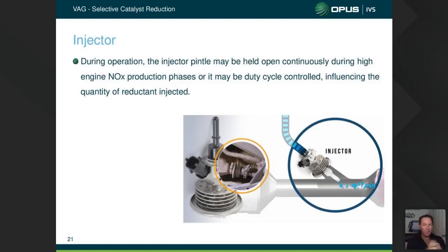The NOx reductant, or the reductant injector, we can open that even under full load conditions. So if we're dumping bucket loads of fuel into that system and lots of compression pressure, big turbo, big boost levels, our cylinder pressures and temperatures go up, so it's a breeding ground for NOx gases. So there's no reason at all, because this is after-treatment down in the exhaust, we can't pull that nozzle open wide under those conditions, going up a long hill under power.